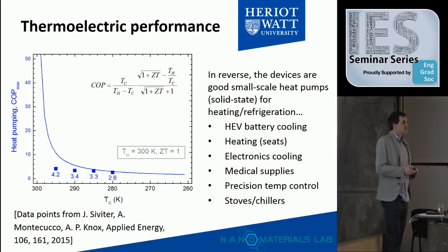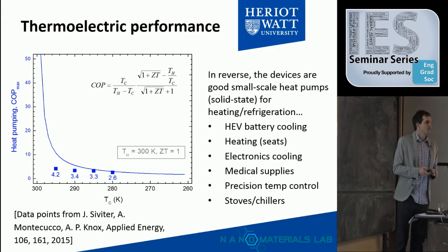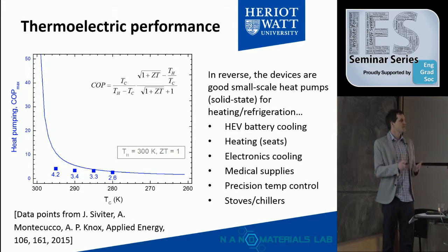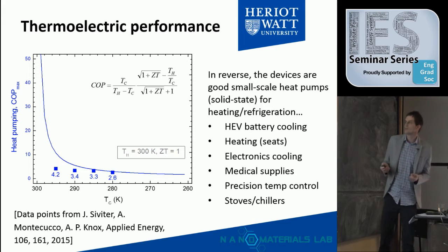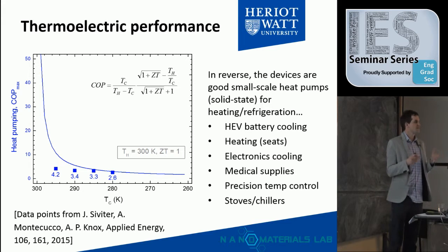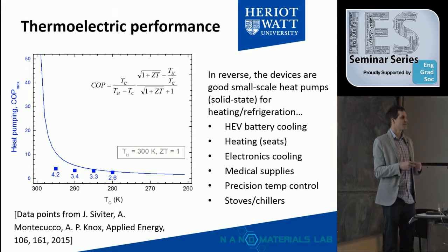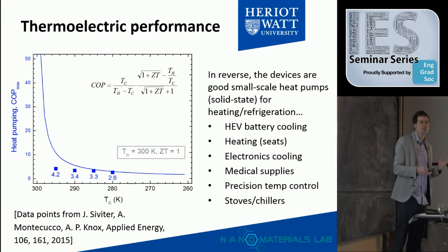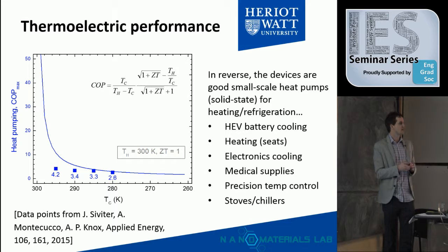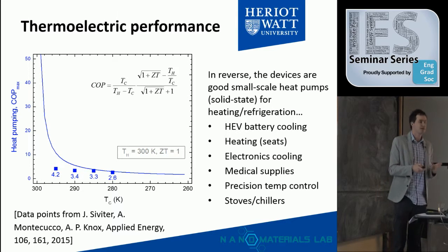The flip side of the devices is that, as well as using them for energy conversion, you can also use them as heat pumps for heating or cooling. So instead of using the hot side, cold side gradient to generate current, you can put a current through the device and move heat from one side to the other. Again, this is better for the small scale, so I'm not suggesting this type of heat pump could compete with air source or ground source heat pumps, but for small scale applications, the solid state type of application can be